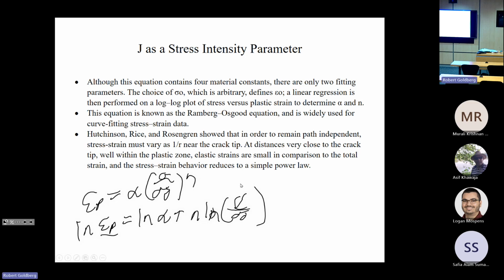And this equation is known as the Ramberg-Osgood equation, and it's a simplified method that's commonly used to do quick and dirty plasticity analysis. Just as we talked about, the one caution is that it really is a nonlinear elastic analysis, because if you unload, you don't account for the permanent strains that are present in your material. So this is the basic stress-strain relation that was used in this type of analysis.